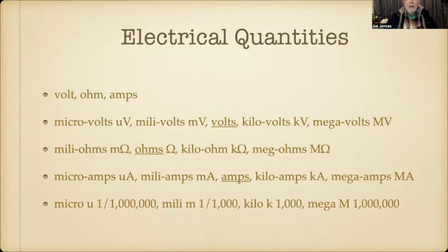And then there's current, same thing. There are amps, which is actually a fair amount. Around the house, when you have 120 volts and plug in a normal 100 watt light bulb, it's about 1 amp, actually 0.8 amps. If you turn on your microwave, it's drawing 12, 14 amps from the circuit, which is a lot of current.